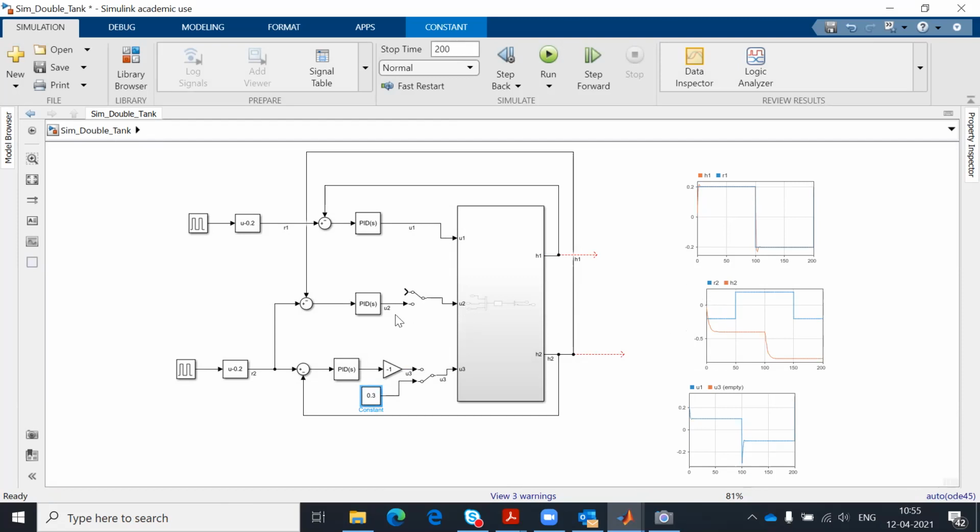Now, when the fault has happened, as I mentioned, you need to have a supervisor. It is called fault detection and diagnosis. It's a block that we will talk about next week. The output of that block is that, okay, a fault has happened and where it has happened. And now we need to reconfigure the controller, and reconfiguration of the controller means that, first of all, you have to design a controller here, or you should have designed it in advance, and now you're ready to switch to that controller. Okay, now you switch and then you let it go.